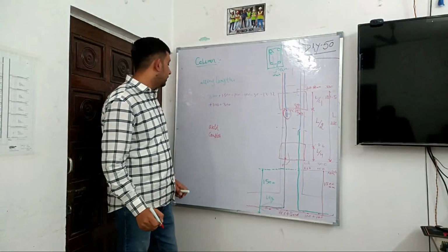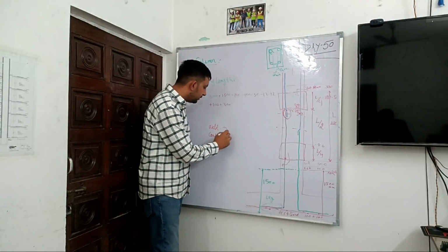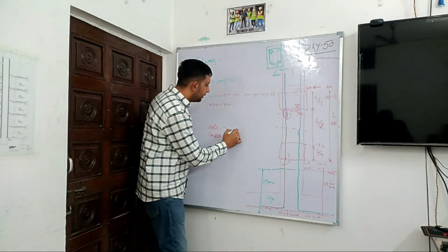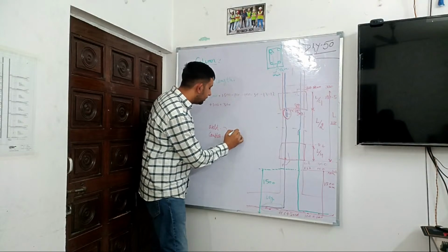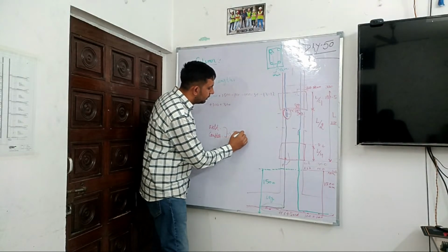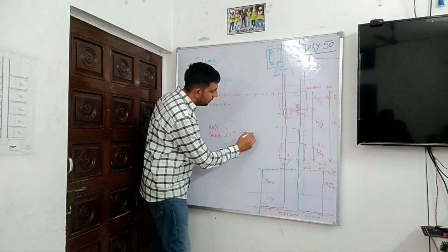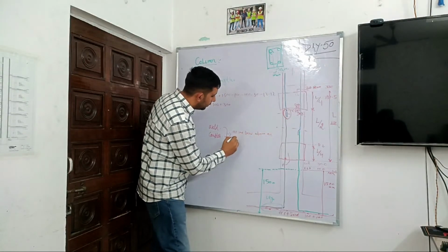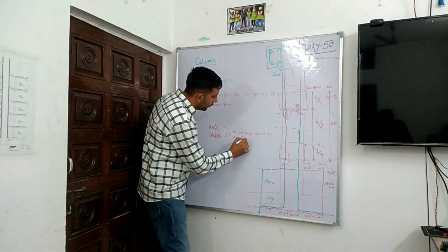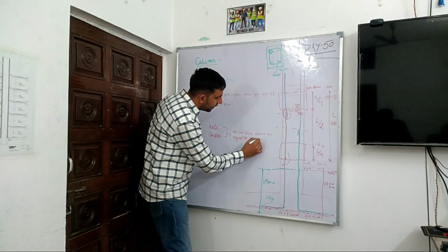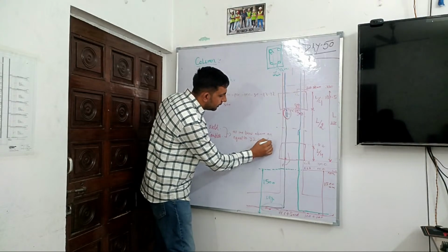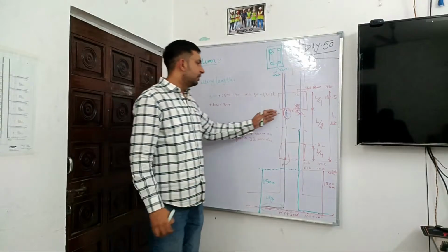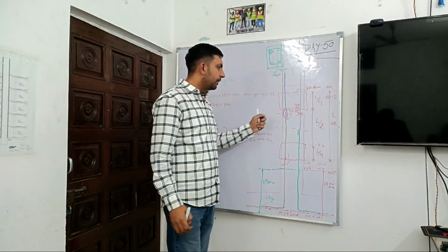These two are also ways. And we will generally prefer these methods for bars of dia above or equal to 32 mm. These methods are preferred for this much dia. Else we will provide the lap method while joggling the bar.